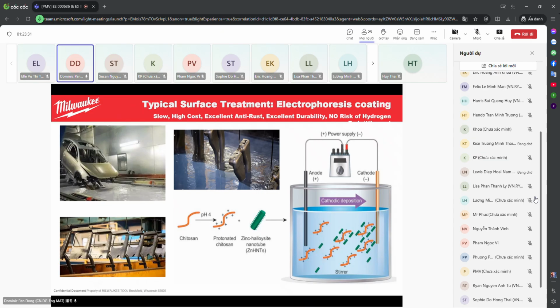And here we go to some other traditional coating. For this one, it's so-called electrophoresis plating. This is commonly used for the automobile, our car doors and all of those plates, the final painting is done by this kind of electrophoresis process. It's reliable, it's good, but the investment of that line is huge, so the cost is also a big concern.